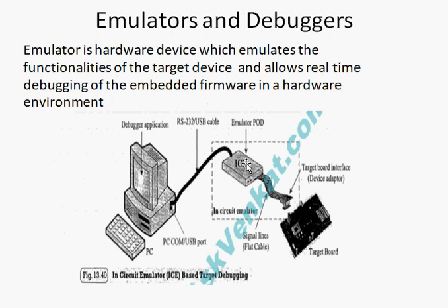So one end of the JTAG emulator was connected to the host machine using a USB port, and one more end was connected to your JTAG connector, which was there in your board. That was also a USB slot itself, if I'm not wrong, and it depends. If you have USB support, it might be there. Sometimes you might have a serial support also. It could be a USB to serial adapter.